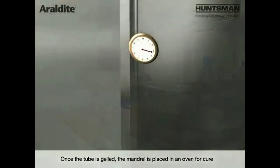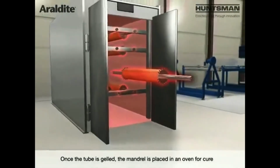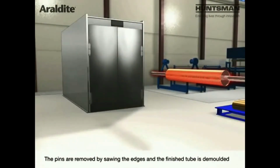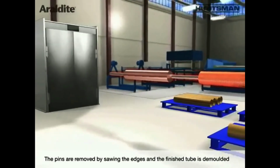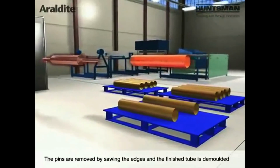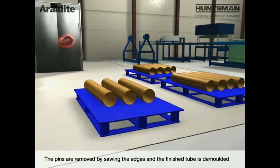Once it has cured, the mandrel along with the composite product will be taken out after the curing, and then the pins are removed by sawing the edges and the finished tube is demolded, and we will get a long cylindrical product with the process of filament winding.